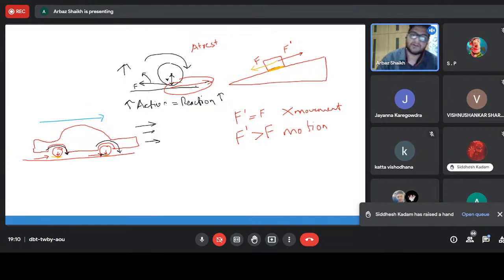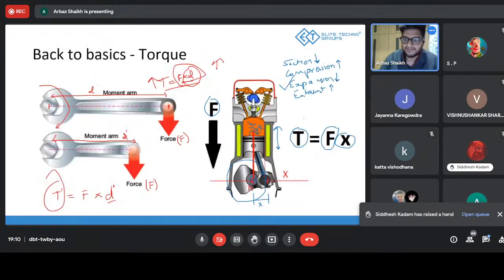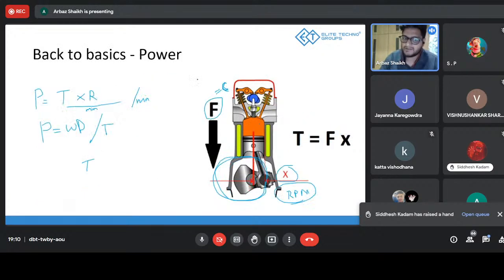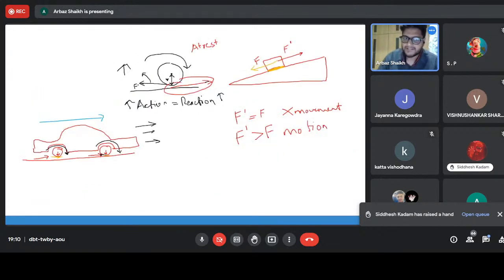We got a radius, we got a rotation, we have a force. What do we get? Torque, you get a torque. Correct. That's what we saw in the first slide, correct? When we have a force and a distance, we get a torque during a rotation, right? So we have this force, we have this radius of the tire, we'll get torque. F multiply R will be torque.